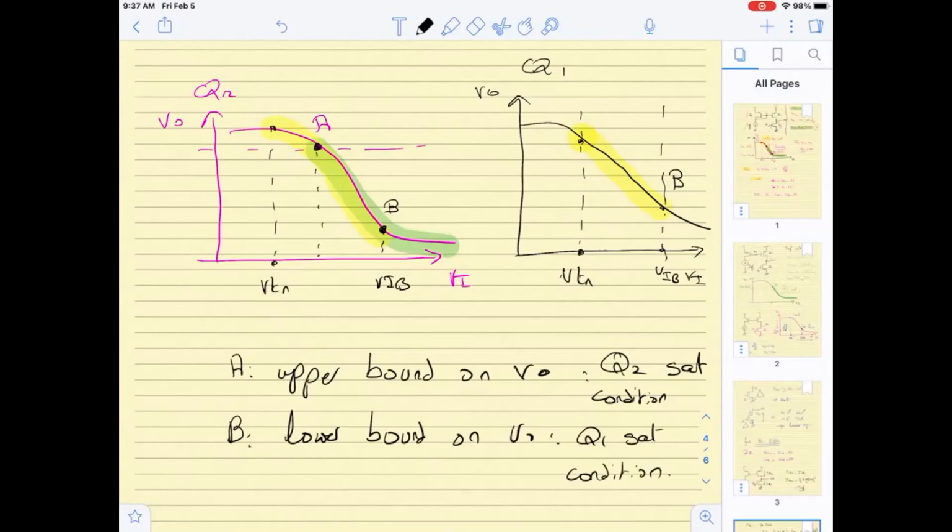Okay, the most important thing in a given problem, if I know that those 2 transistors are going to control my performance, I need them both to be in SAT. Each one of them, if I write the saturation condition for it, is going to create for me 1 bound on Vout. Is this clear now? Yes, all good.